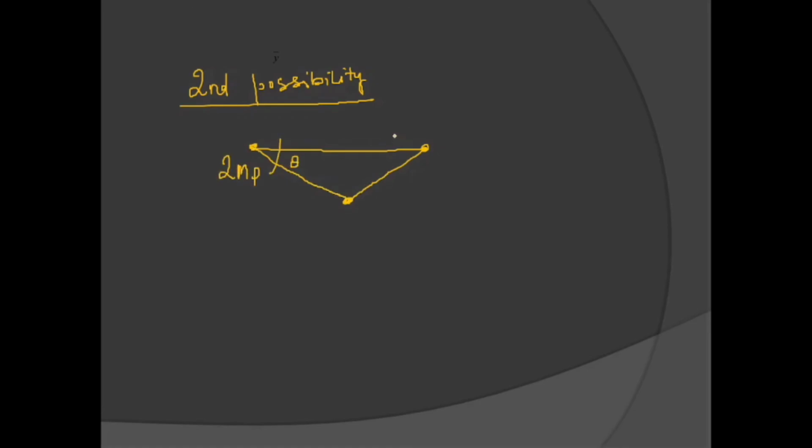into theta. This is also a theta because a central concentrated load is there, and this is also MP because at the junction when two sections meet, the minimum value of MP is taken. This is theta, this is theta. So total MP into theta, 2 MP theta, MP into theta plus theta, total 5 MP into theta. 5 MP into theta is equal to P into 2L by 3 into theta.